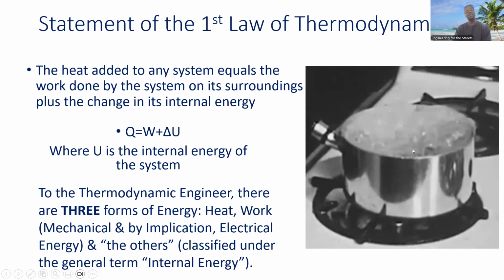In fact, at the point of boiling, you might see that the temperature does not change, and so the change in internal energy will tend to zero, while all the energy you supply will convert into work: displacement of liquid water and then generation of steam. So steam will start escaping.